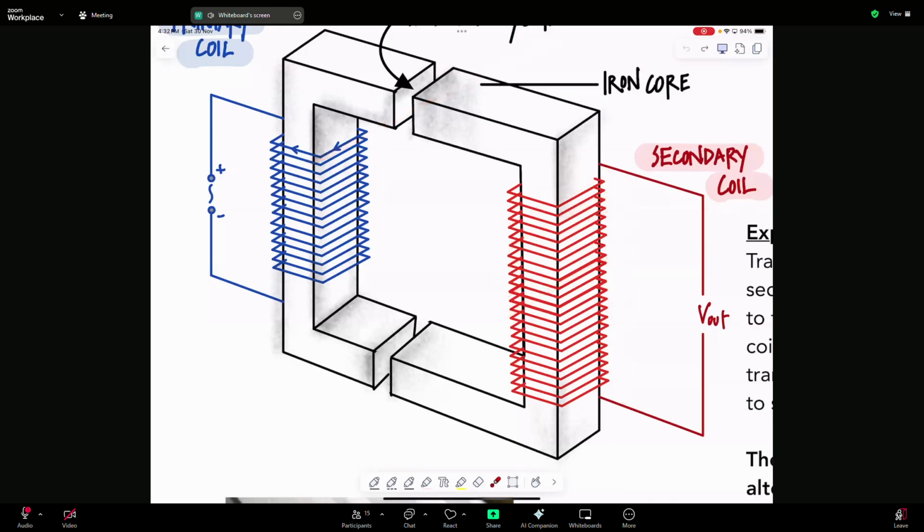And it's not 1:1. Just imagine one coil producing a flux cut by one coil. It's a 1:1 cutting. But if one produces a flux and 3 of them cut it, EMF can be 3 times because 3 of them are producing EMF across them, right? So if we can increase the number of turns here, then the voltage increases. EMF. But there's no free voltage out there. So what's the catch here? Current, because our power has to stay the same. This is very important.